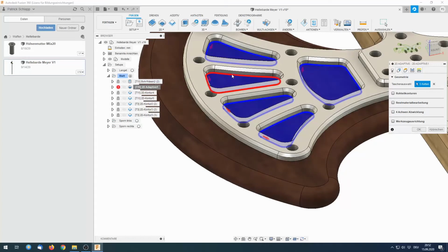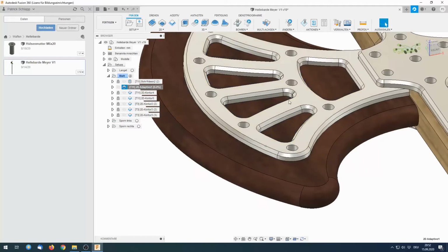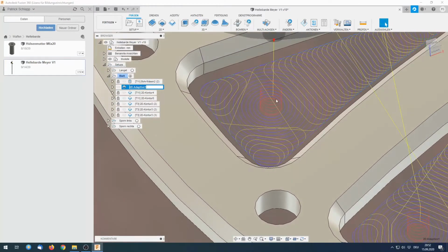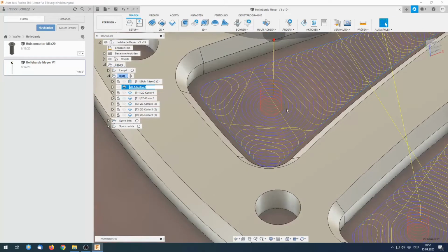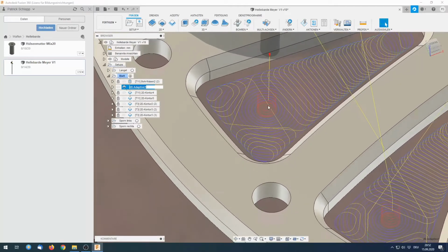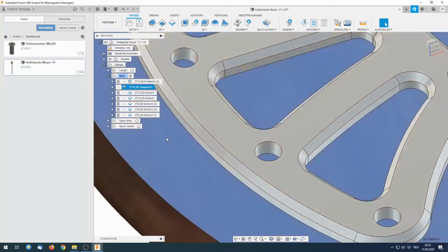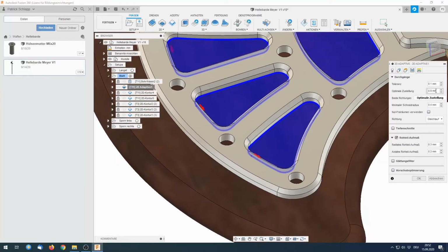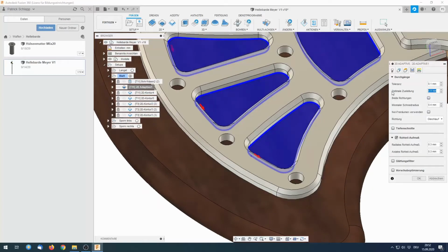the computer will take care of making sure that the end mill has always the same load on it. So you can see like it's circling down in here, and it always makes sure the end mill is only plunged in an amount I specified in the operation. So I can specify how much radius of the end mill has to be in the material optimally.